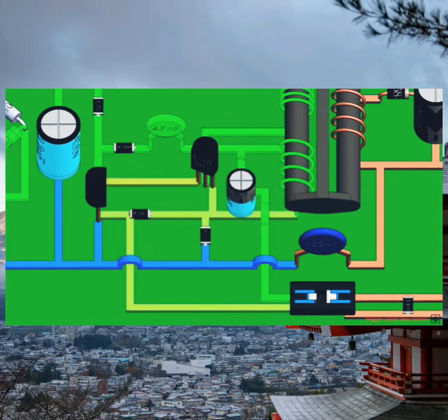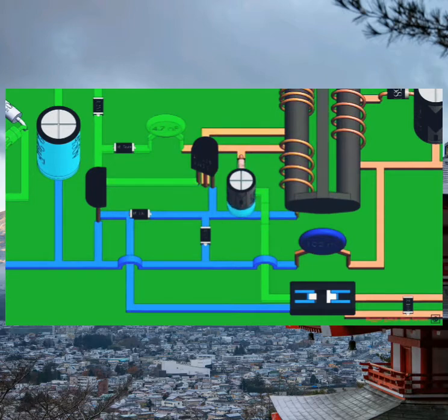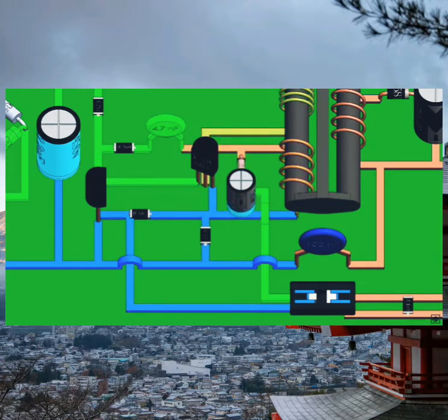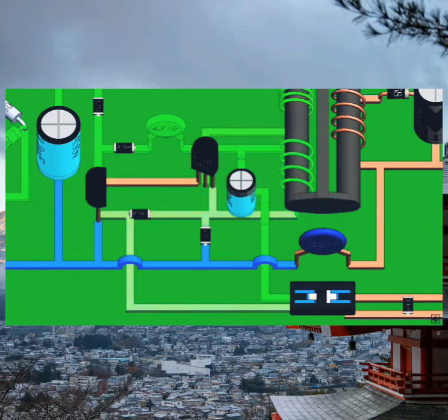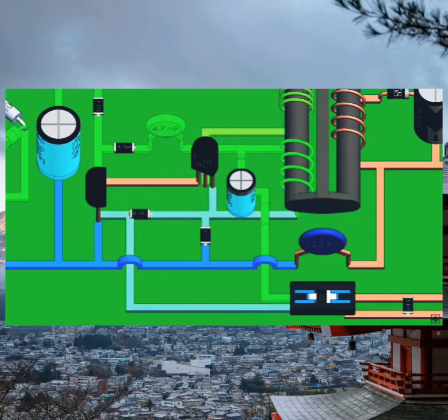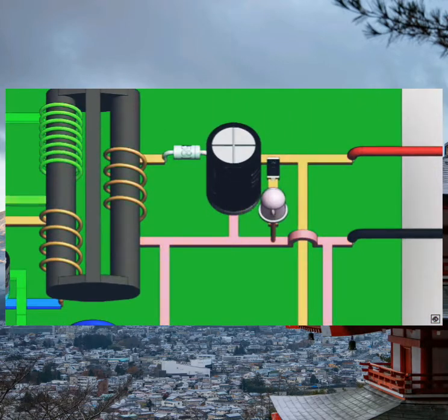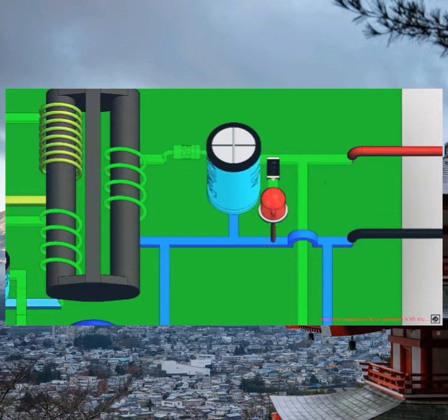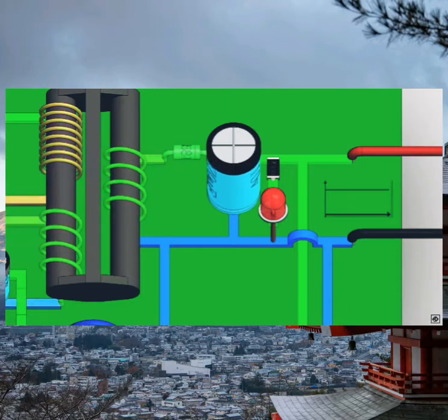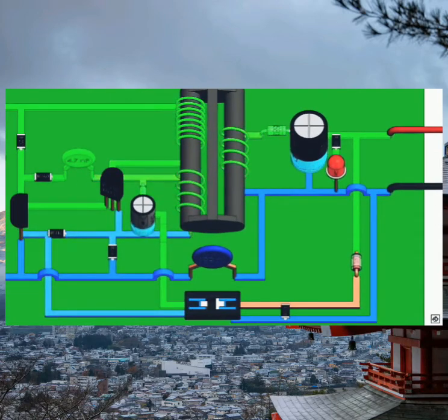At the same time, the voltage from the auxiliary also turns the diode on and charges the capacitor and flows to the optocoupler. This diode and capacitor convert the AC from the auxiliary coil to DC for the optocoupler. The current is also induced in the secondary winding. This is converted to DC by a Schottky diode and a filter capacitor. It is indicated by the LED. But what if the voltage is more than 5 volts? Hence we have a feedback circuit.